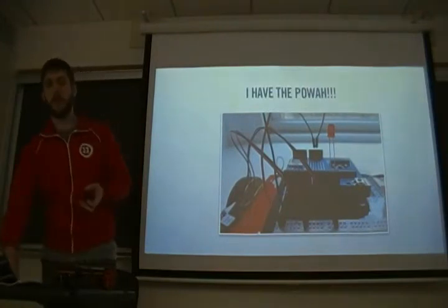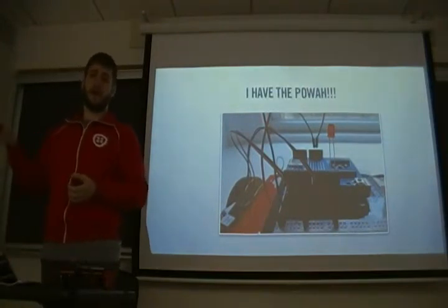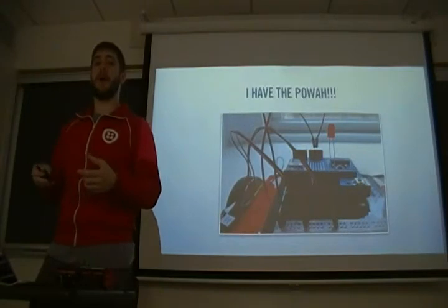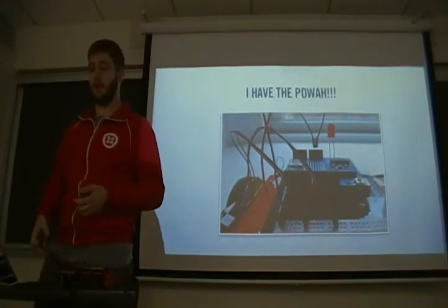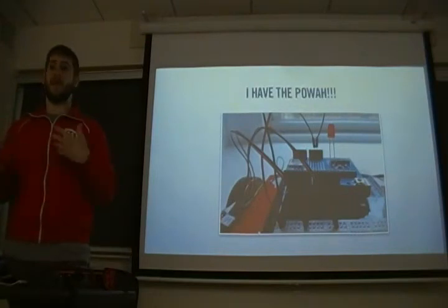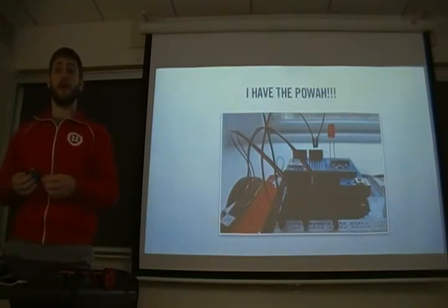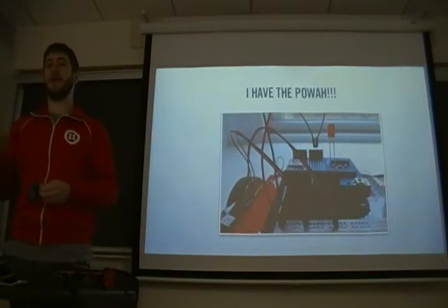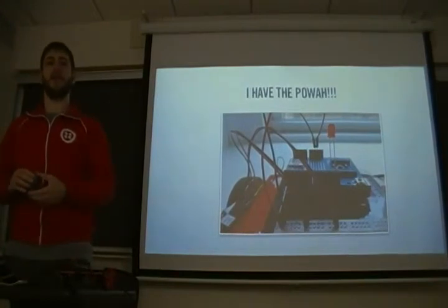So what you can do is plug the Arduino into a power source, and it can independently power all of its sensors and motors, right? The only time you would have to worry about external power sources is if you're doing high-capacity stuff, right? If you have big motors or really demanding chips.